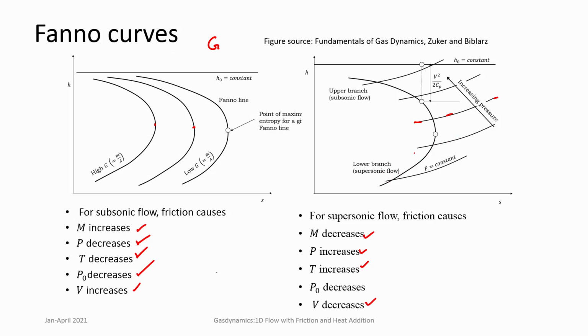Okay. So, if you have understood these Fanno curves very well, then you will be in a position to understand Fanno flow very well, because just by means of this particular curve one can completely describe the Fanno flow. So, when a flow is happening, the point moves from initial point 1 here to another point 2 here, which represents a flow through a duct of corresponding length L. Okay. So, you can say this is the duct of length L.